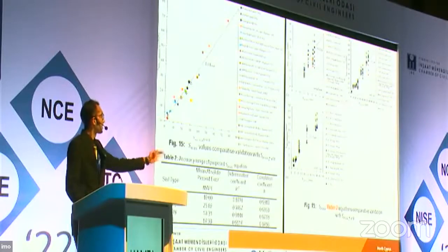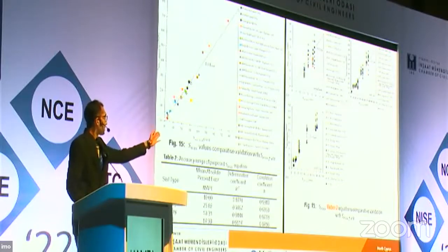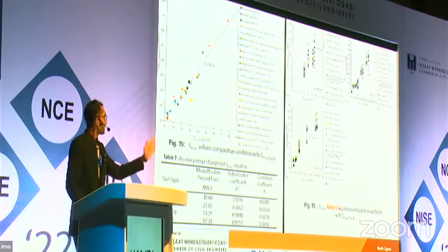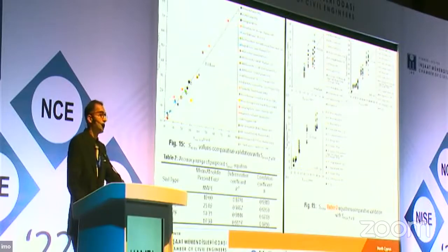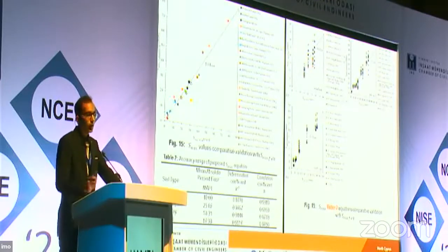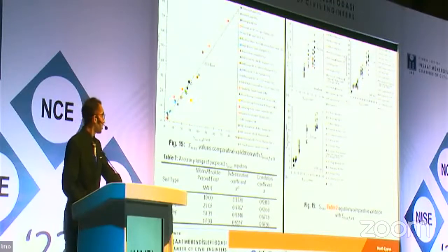And if you see figure number 15 on the right hand side, I have substituted all those table number 3 equations, and we can see that in major cases the maximum settlement was quite underestimated, which we have to avoid, because tunneling projects include many sophistications and many complications.